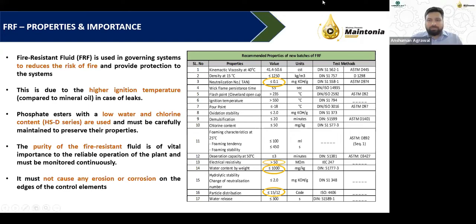Great. Thank you so much for reminding me of that. Apart from these four properties, there is a property called foaming characteristics or foaming tendency, which has come up recently with a lot of users of this fluid, wherein all the other properties were probably intact or not much deviated, but foaming observed at the tank level was very, very high.